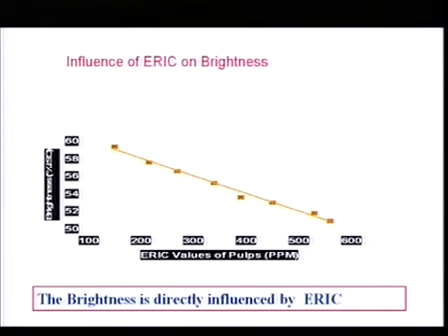If you have a higher amount of ink particles, these are very small particles, ink. For example, at 600 ppm here, you can see the brightness of that newspaper is very low. As you remove ink in your flotation cells and washing devices, you are lowering the ERIC, less residual ink is present on your paper, you are brightening the fiber.